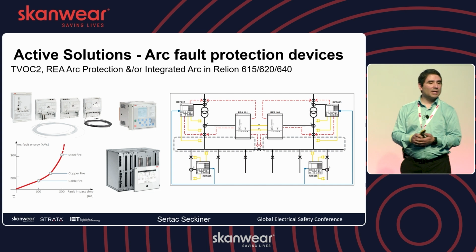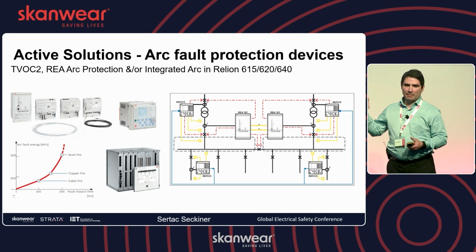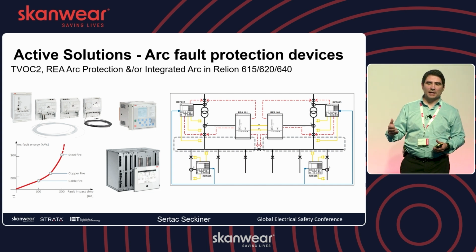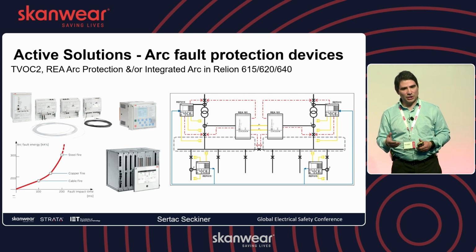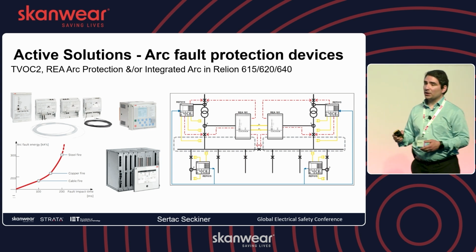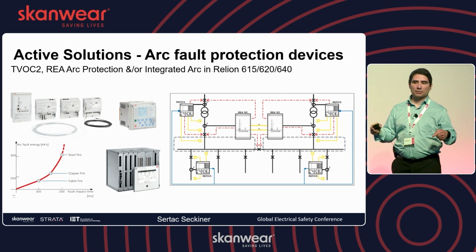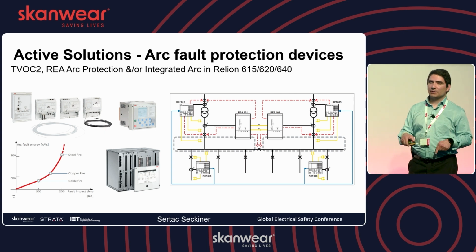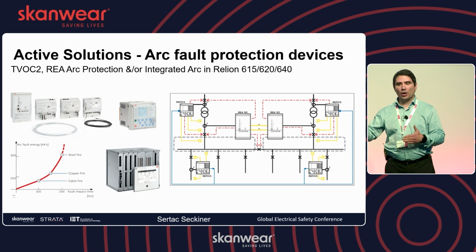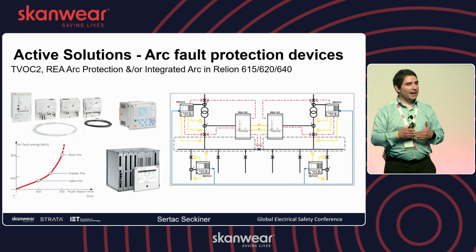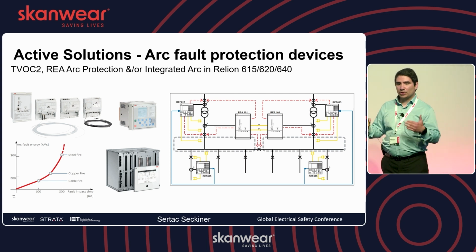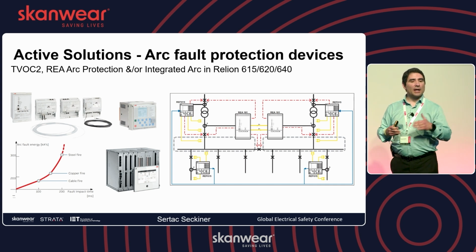types of protections. The good thing is here, because we've mentioned the cost and effectiveness, now we don't really have an excuse not to use arc flash protection, because in most of the protection manufacturer relays today, there is integrated arc flash protection, which doesn't really add much to the cost. So you can always include the protection relays and the arc flash protection at the same time to save lives. So there's really no excuse about the cost of an arc flash protection implementation.